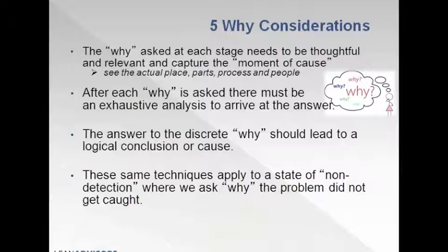And why wasn't there enough air circulating? Well, there wasn't enough air circulating because the filter was clogged. And then the guy looked at it and said, why is the filter clogged? Well, because it hadn't been cleaned. Now, at the end of this process, the guy looks at it, and sure enough, that filter was clogged. But here's the point we're trying to make. The machine tells the maintenance department when to clean the filter. There's a little green light on the machine that blinks and says, filter clean required. That's being ignored.